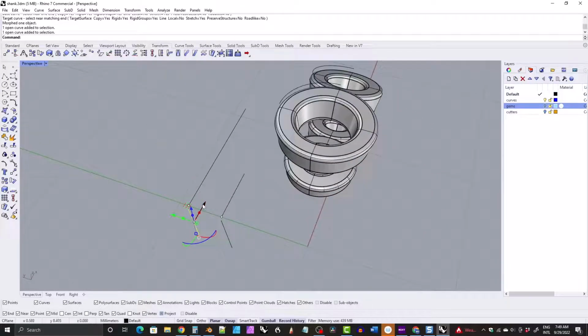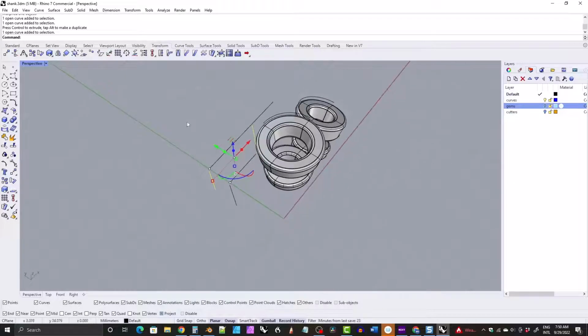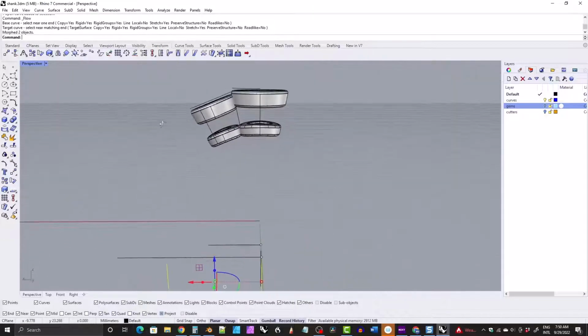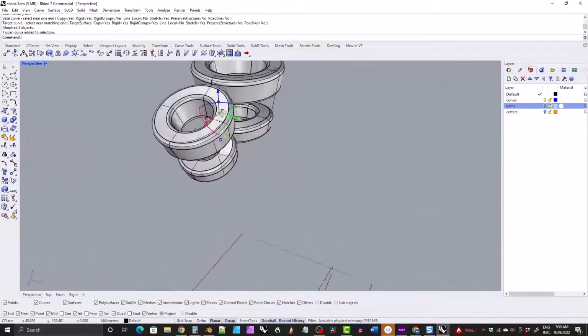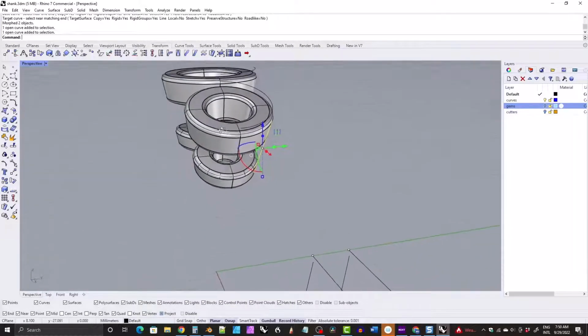Now we're actually going to duplicate this line. So I'm just going to pull this arrow here, and while I'm dragging it, I'm going to tap the Alt key, and now you can see I'm making a copy. So I'm going to flow both of these lines from this curve over to this curve. And you can see here is one line and here is the other. All right.